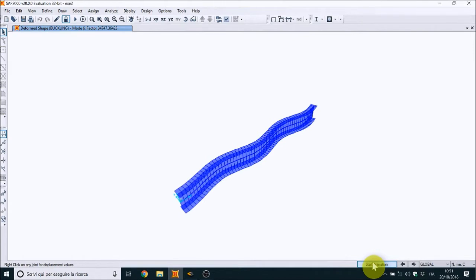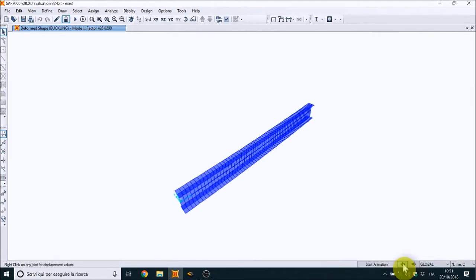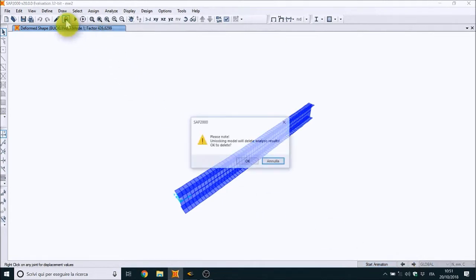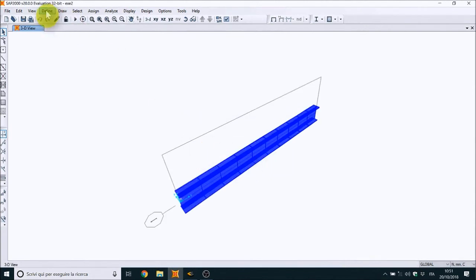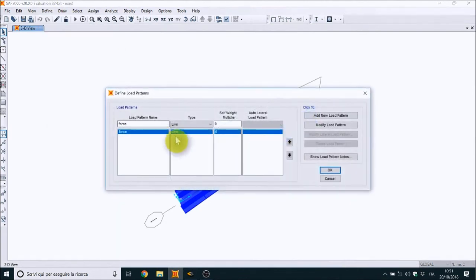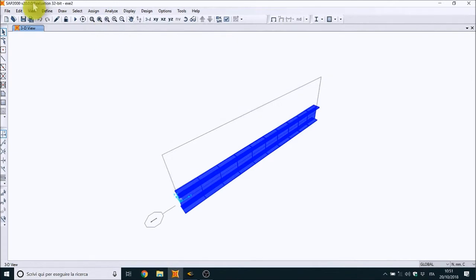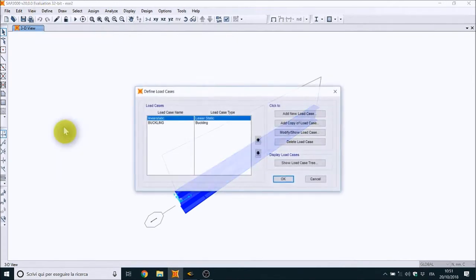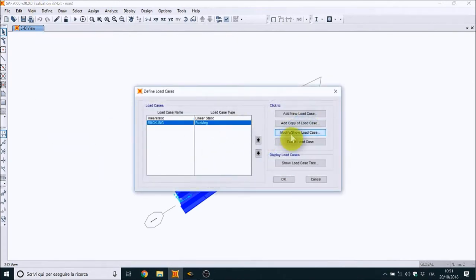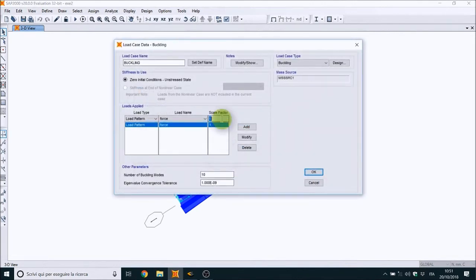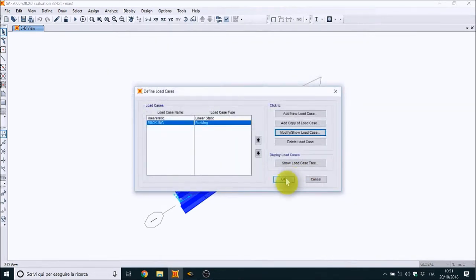Of course, if I put a multiplier 10 times, I will obtain a 10 times lower buckling factor. So now I have 426.8. If I put here, in the load cases, a factor of 10, since everything is linear, I expected to obtain 42.68.